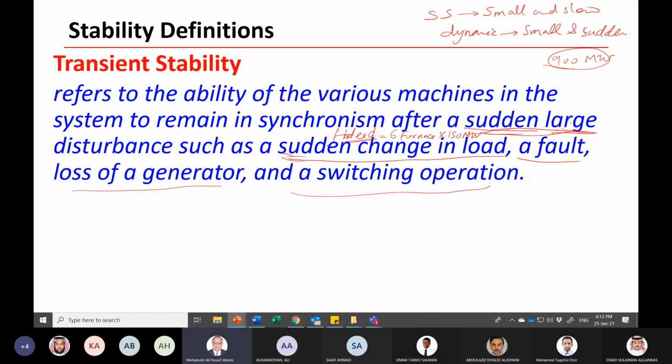I had a chance to visit Hadid and see this, and they said that we have to communicate with the Saudi Electricity Company about the scheduling of these furnaces. So the power system operator here should be aware of the time when they switch on the furnaces. So he has to have a spinning reserve to cover this. Otherwise, the system will be in trouble.